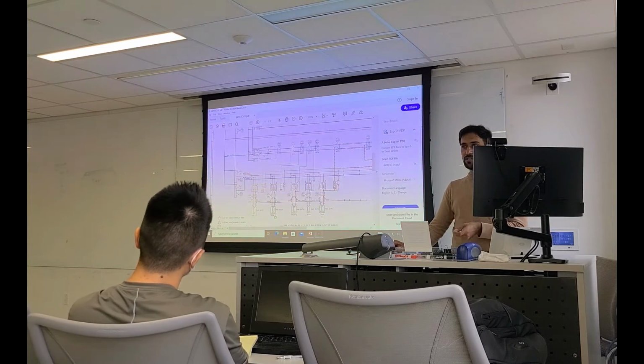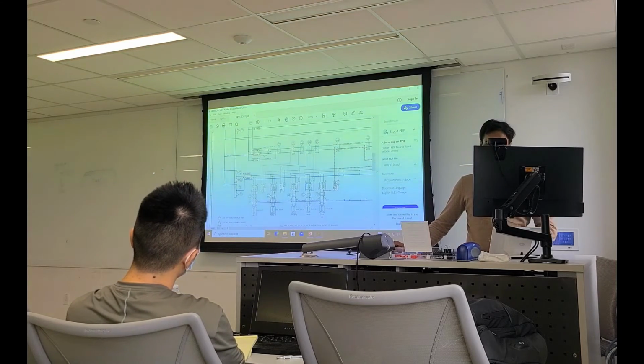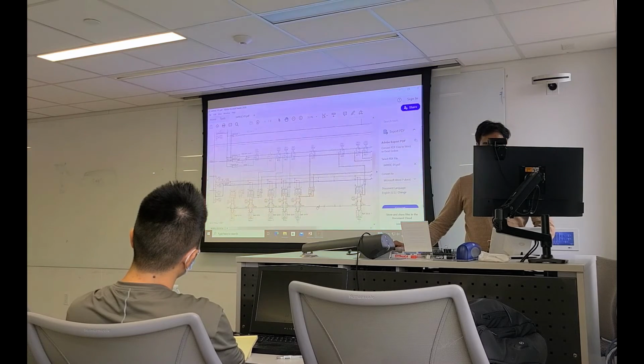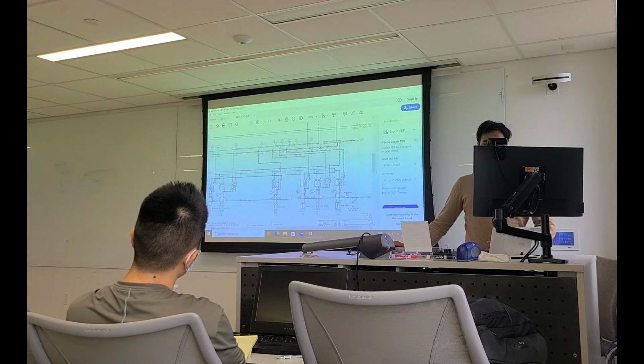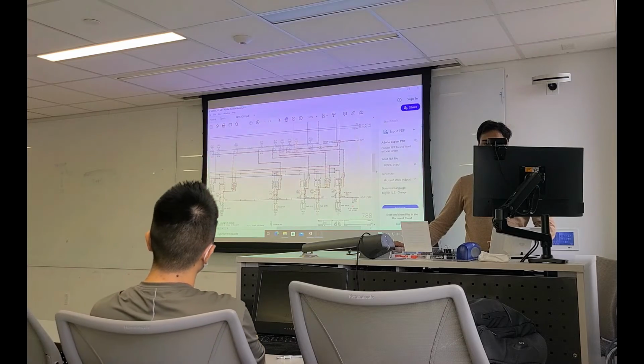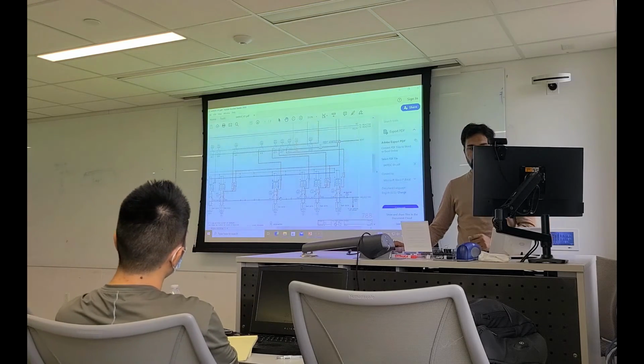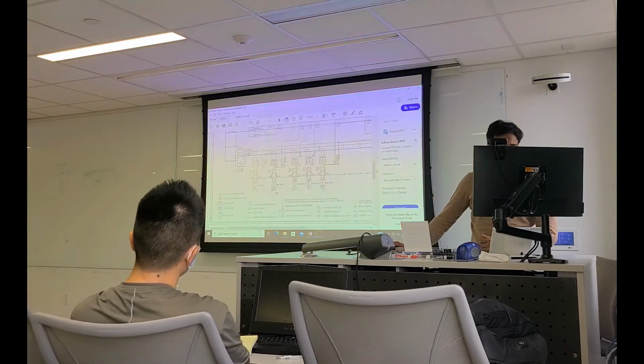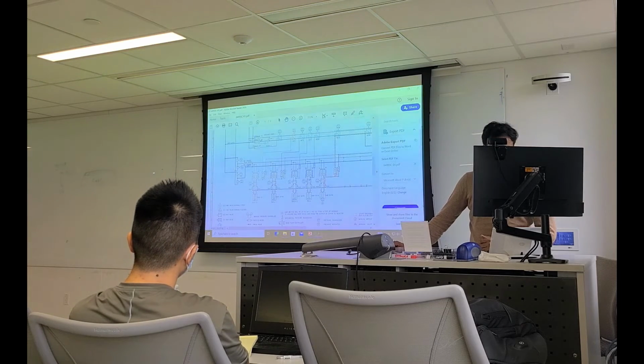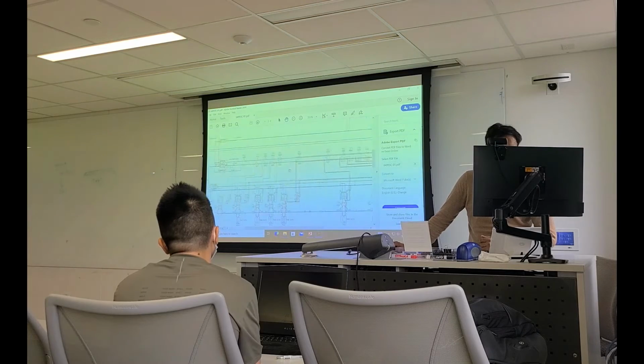Okay, through the recipe you can decide which gas should go. Like in case of triethylindium, you cannot use hydrogen, so we are just directly flowing nitrogen, or argon we can use.